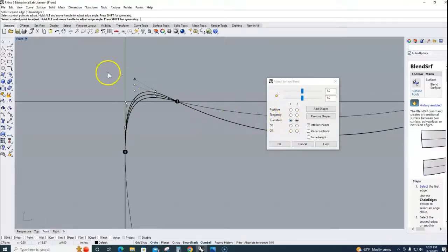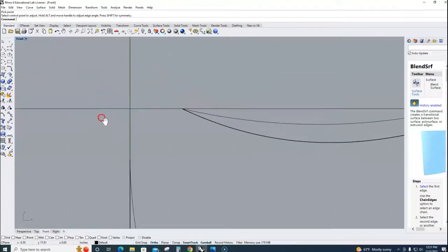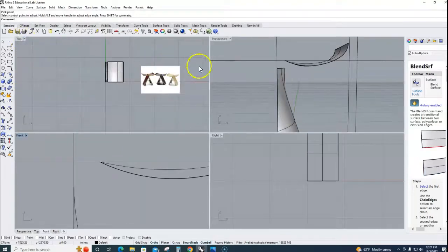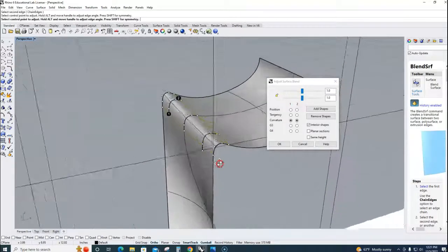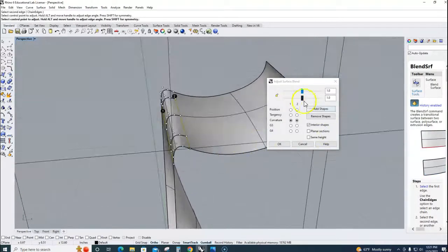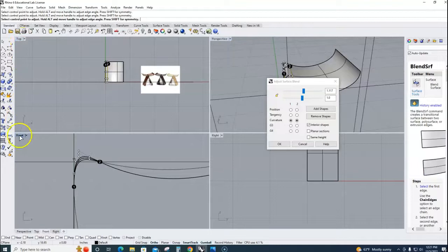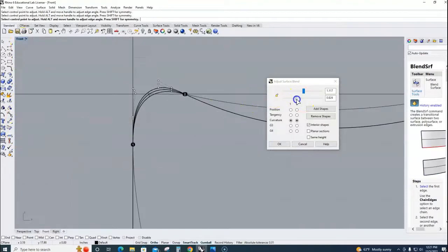So I would just say take curvature, but oops, see. Shoot, sorry guys, I am pushing all kinds of key buttons that I shouldn't be. So let's do it again. Blend curve near the same area. Good deal. I like it. You know, you can adjust the curves accordingly like this. So if you come here to the front view, you can see curve 2. If you want it a little bit tighter, maybe this one should go up a little higher.